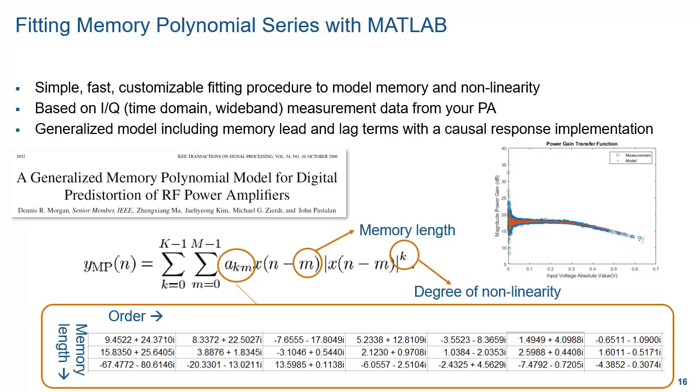Now, let's say that we have a model of a power amplifier that we have identified using this procedure. There are many ways in which you can linearize a transmitter with multiple chains. So you might have to perform an architectural exploration among the different options.